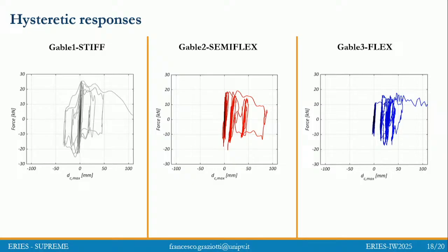And again, I'm not only referring to the gables, the triangular thing, but also to a simple one-way bending beam, a one-way bending wall responding out of plane. It would be very important to understand how this wall is responding to the very different response at top and bottom.